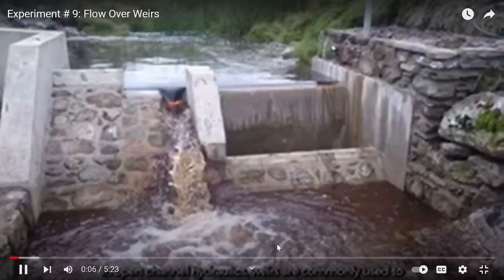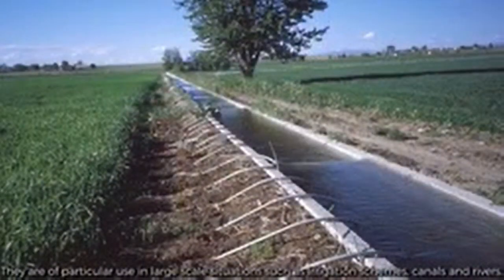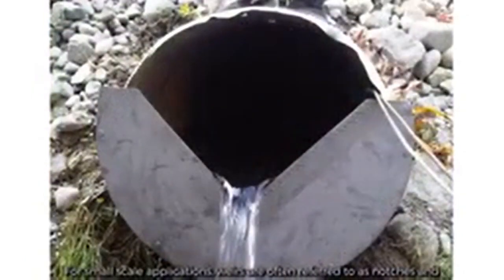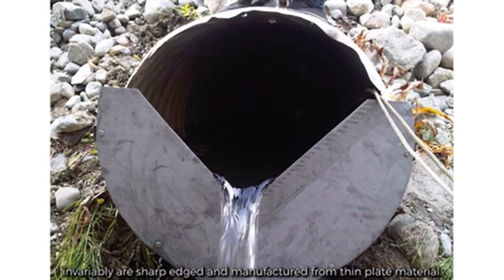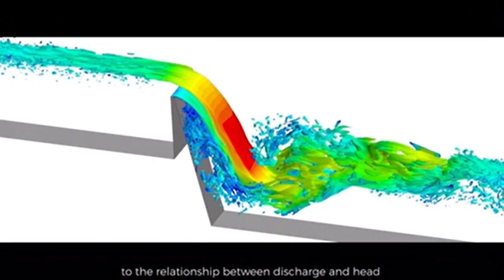In open channel hydraulics, weirs are commonly used to either regulate or measure the volumetric flow rates. They are of particular use in large-scale situations such as irrigation schemes, canals, and rivers. For small-scale applications, weirs are often referred to as notches and invariably are sharp-edged and manufactured from thin plate material. The flow pattern over a notch or weir is complex, and there is no analytical solution to the relationship between discharge and head, so a semi-empirical approach has to be used.